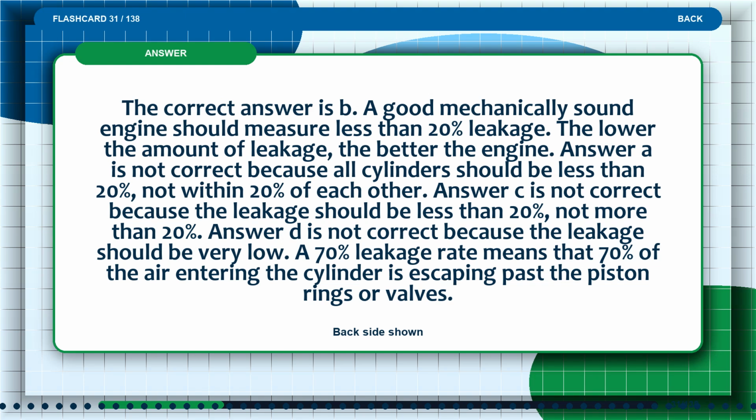The correct answer is B. A good mechanically sound engine should measure less than 20% leakage. The lower the amount of leakage, the better the engine.